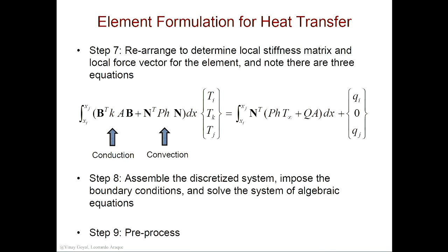I'm sorry. Okay, Aaron, you have a question? Yeah, so K and A are scalar or? K is conductivity, and it's a scalar quantity. So you know the conductivity of the material, just like you know the modulus of the material in a structural mechanics problem. And there are experiments that you can do to get the conductivity of the material. And A is a cross-sectional area, which can vary as a function of length, just like we did the bar problem that was varying cross-section.